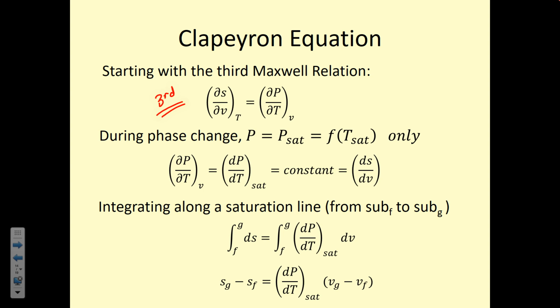So that's going from liquid to boiling. We haven't looked at other regions of that diagram, but if we were to go from a solid to a liquid, or from a solid to a vapor, sublimation, then we could see similar trends that the saturation pressure and saturation temperature are going to be linked during any kind of phase change problem, as long as we're changing between two phases.